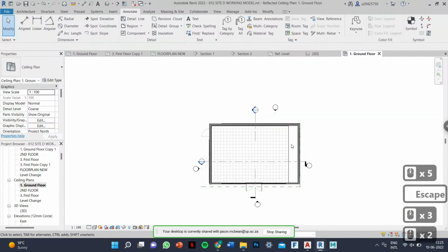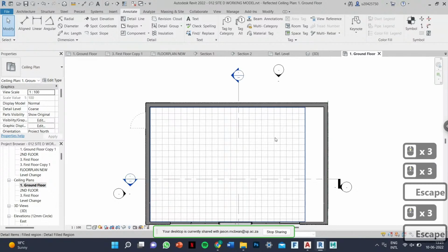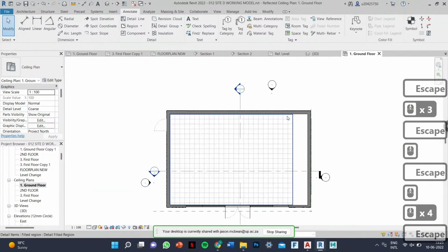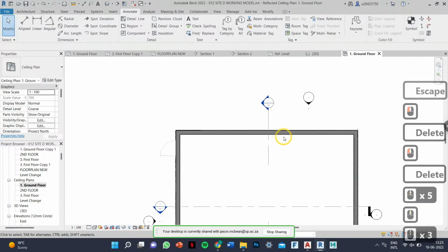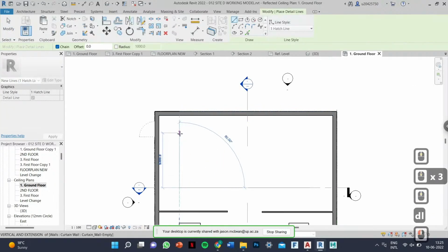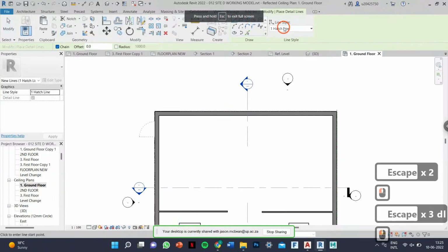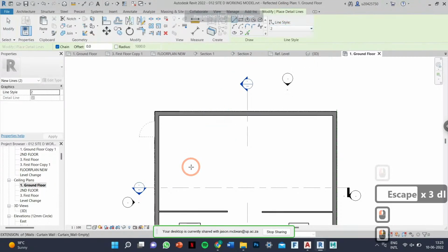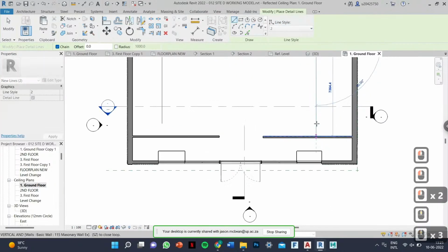Here's my ceiling plan. Wait, so my ventilation, does that count as my ceiling plan? Oh, you're going to see that underneath here now. Oh, because it's exposed. Yes. Okay, in that case, what you would have seen now, you would have seen it just like that. Detail line work. Now you're going to use, so let's just go here to detail line. Watch this, line weight 2. Watch how quick this is. So say now, this is my reticulation or my ventilation.